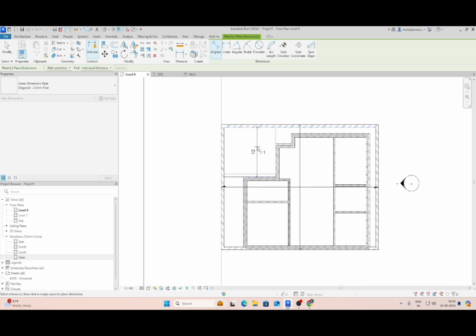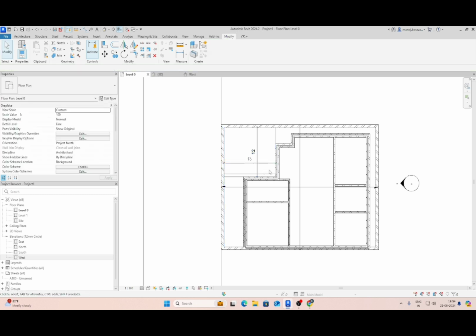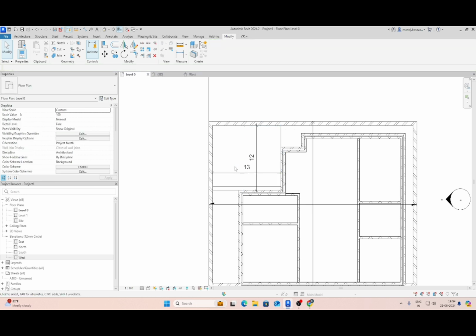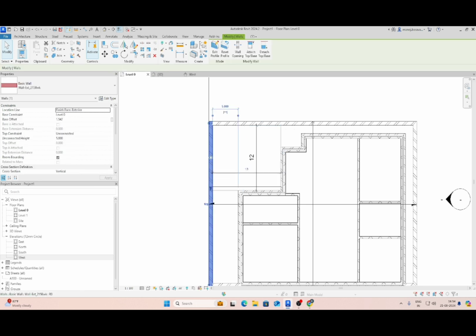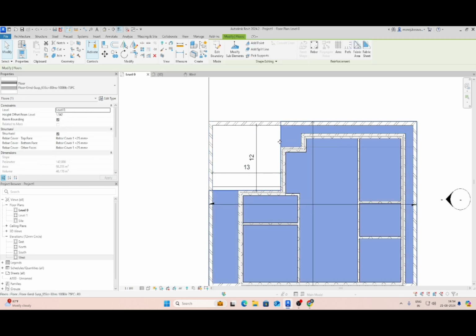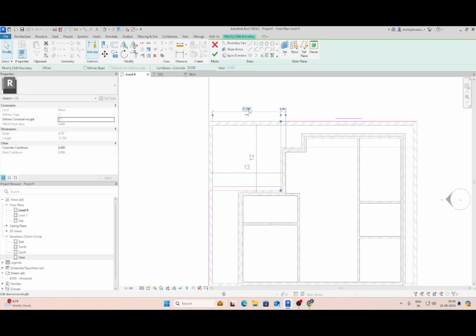Here to here it is 12 feet, correct? 13 feet. The client had requested a 14 feet car parking, so we'll go with, yeah, there is going to be a gate here that will give us a few more dimensions, adding here, making it 14 feet, but the slab is already given at 14 feet here. Make it 13.5.